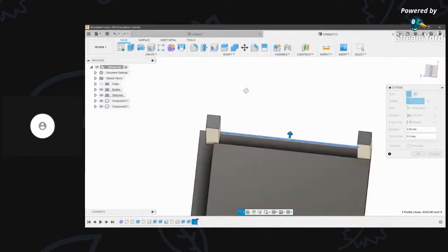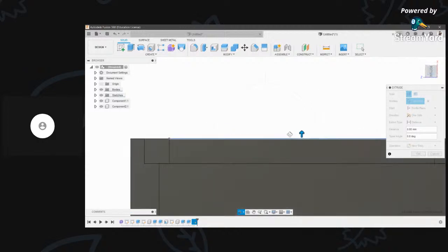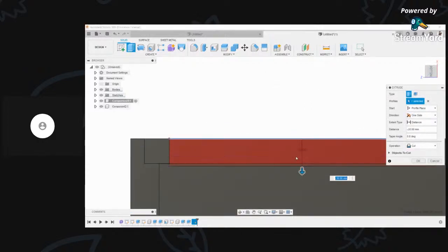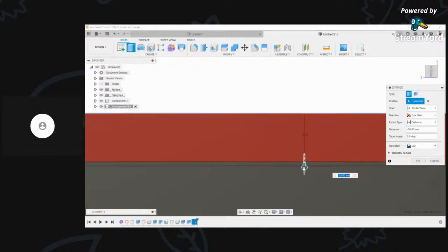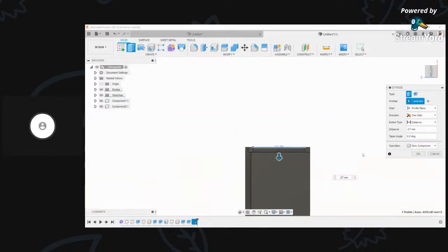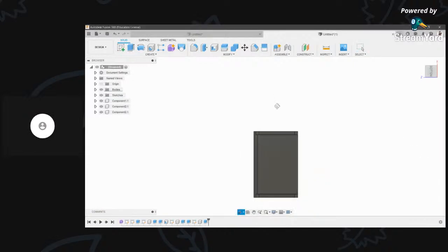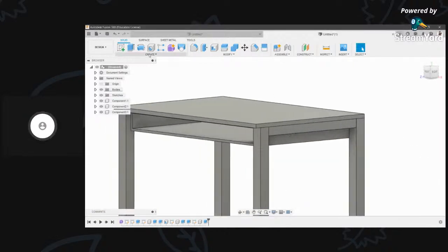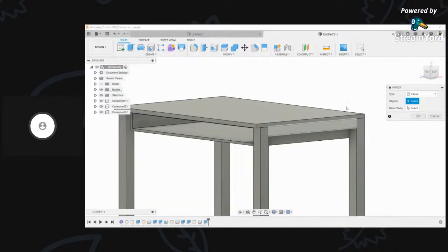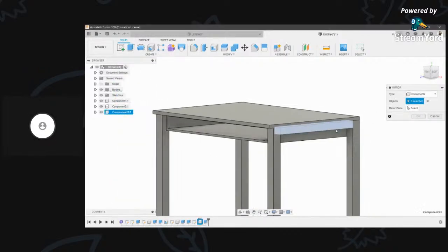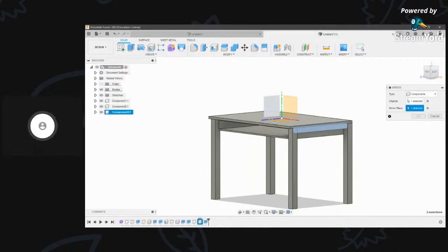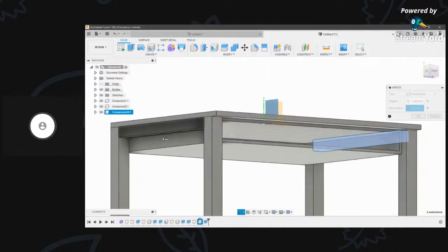And I'll extrude this up to minus 27. Yeah, component. And I'll also mirror the same thing onto the other side as well. So just go to mirror, choose the component, choose this, and then choose the plane as right plane, and then it will be copied here like you can see.